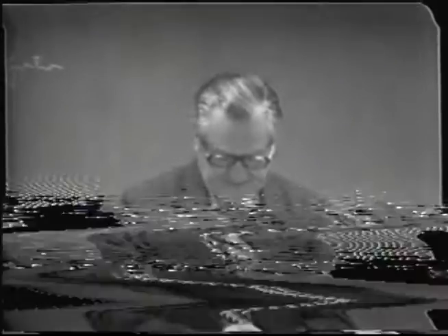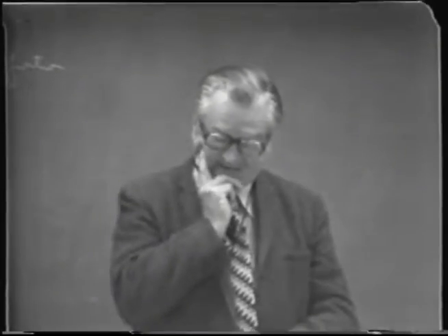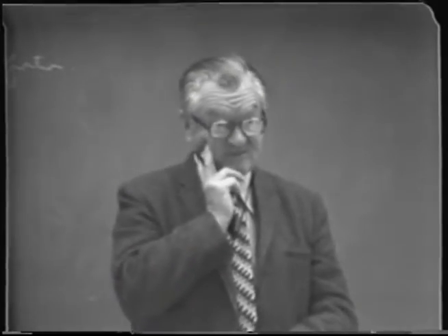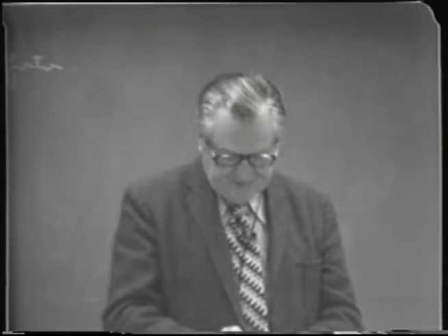Now, what I wanted to call your attention to looking at this is that for systems such as this, when you have very low percentages of a solute like isobutyl alcohol in water, let's say less than 1%, which is a situation that we frequently meet up with or have occasion to consider in our practical systems of alcohol water systems, you can see that the composition of vapor is greatly enhanced from that of the liquid.